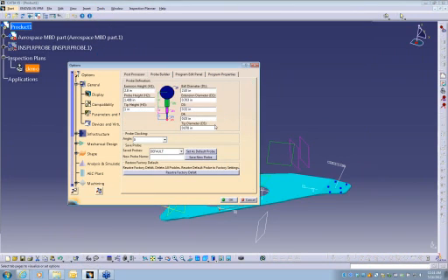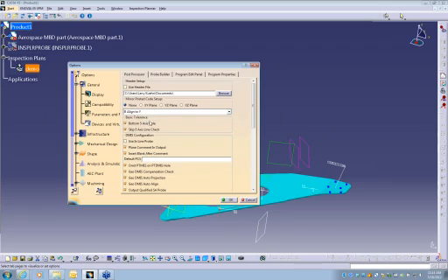we have a probe builder. So you can go ahead and build your own probe and save different probes. We have a customer that actually modeled their 5-axis head because they use this for on-machine probing. It's just a CATIA part that's embedded into the software, and then we have these parameters that you can change, the length. We also have post-processor settings here where you can mirror the program and do some different things with some of the DMIS code and stuff. So this is right in your tools options.